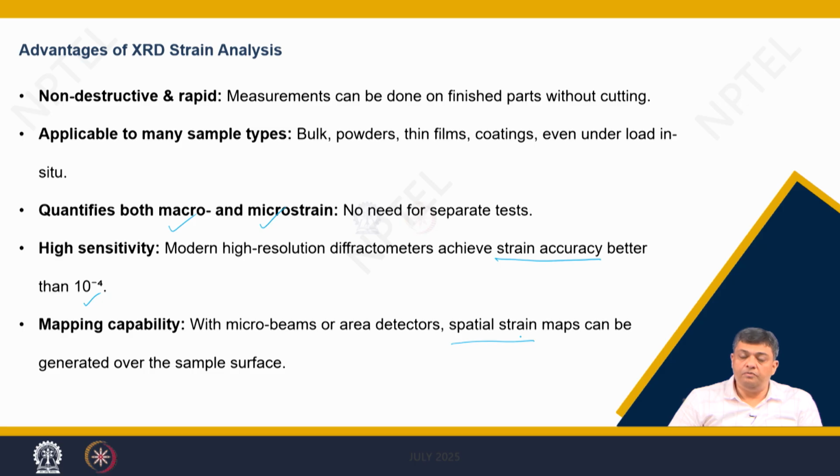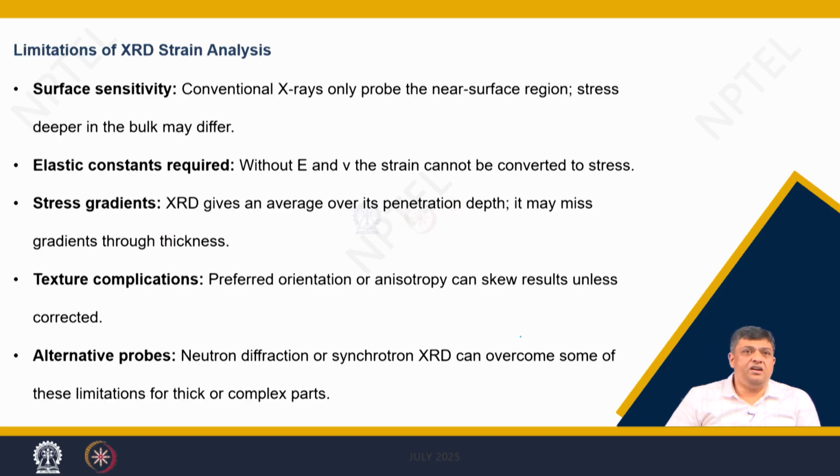which becomes very useful if you are trying to use certain materials for electronic applications or mechanical devices. But there are limitations: it is mostly surface sensitive. You need the elastic constants beforehand. Sometimes there is a stress gradient, because X-ray gives you an average over its penetration depth. Therefore, it may miss gradients through the thickness.